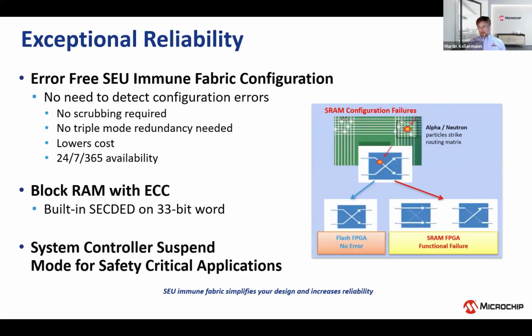So what's good on security? What's reliability? The special thing about the Microchip FPGAs is that they're based on flash technology or on Sonos technology, which is also a non-volatile process. And that means that you don't have to send in a bit stream every time that you power on the device. The configuration is stored inside of the FPGA directly on the floating gate of the flash cell, and they only need to be programmed once. That's typically in your factory, but you can also do that later on in the field if you need to do a field update. So that's also a perfectly valid application.